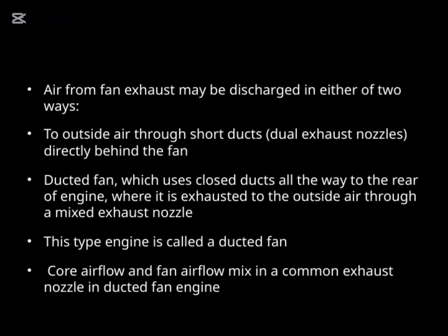Now, let's talk about how the air from the fan exhaust can be discharged. There are two main ways this can happen. The first is through short ducts, known as dual exhaust nozzles, which direct the air straight outside through openings located right behind the fan. This setup allows the exhaust to exit directly to the outside air.